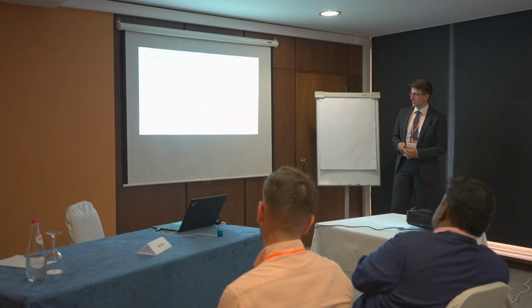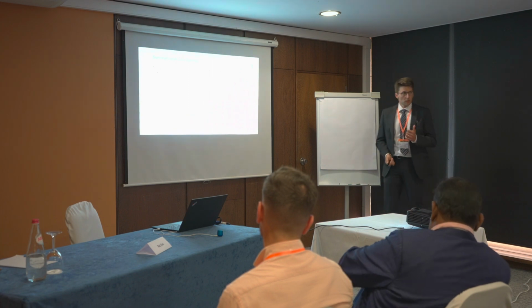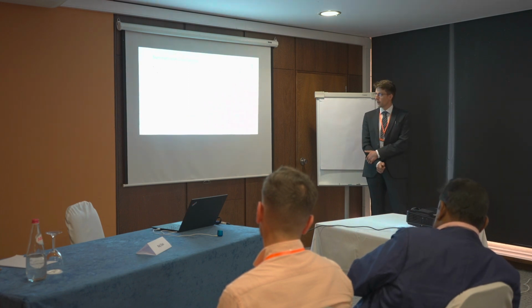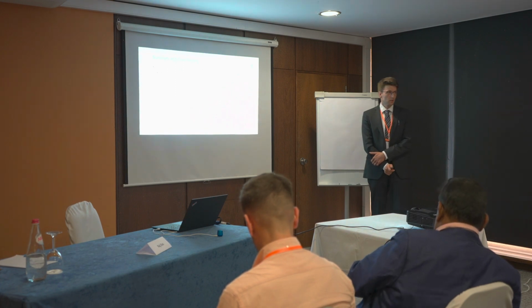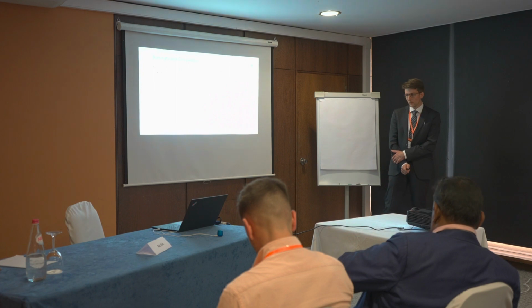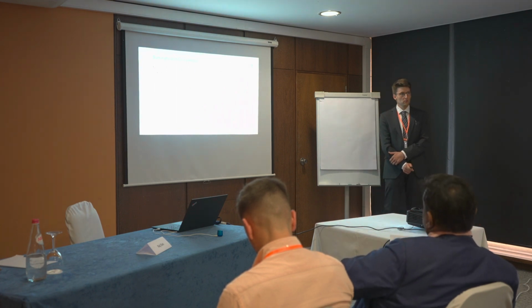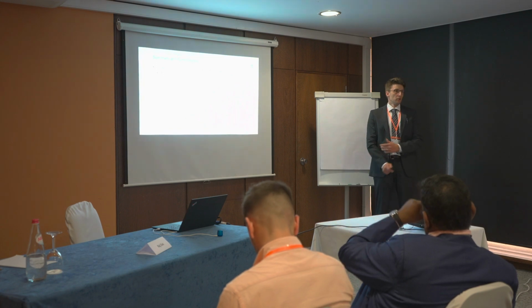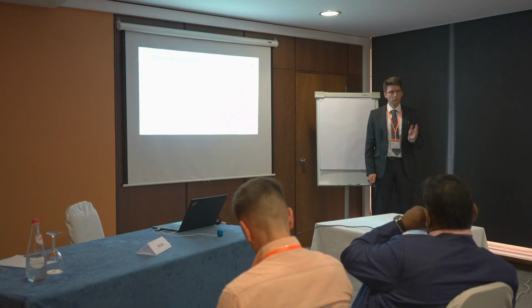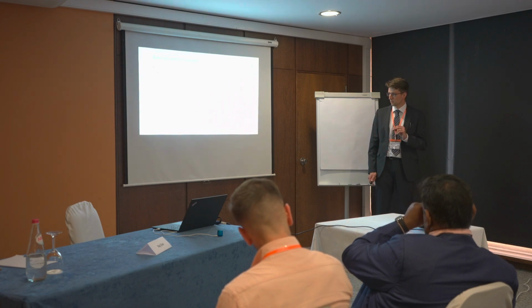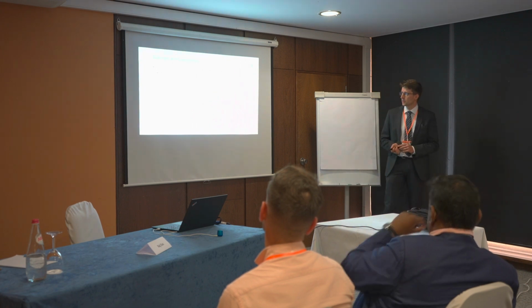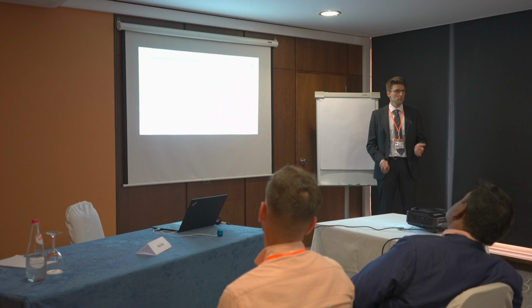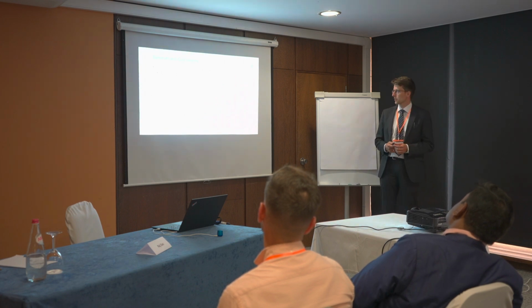So, let's summarize my talk. The most important thing I think is we have a consistency here regarding conservation of momentum. During a classic dynamic calibration, you assume the conservation of momentum for the bars apart calibration, but you assume that there is no conservation of momentum during the bars together calibration part. But in this method I presented here, there are no assumptions at all. We just compare measured signals.